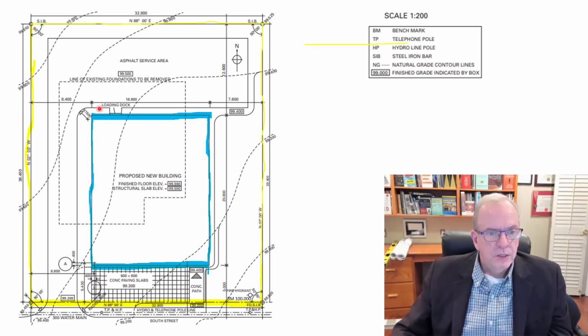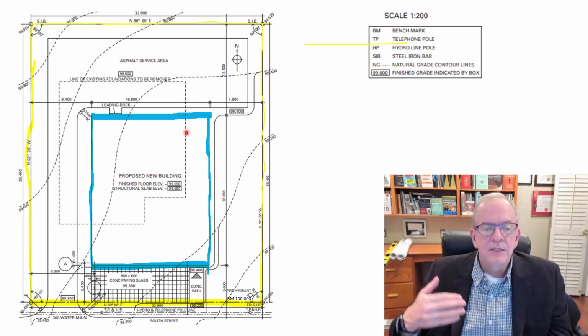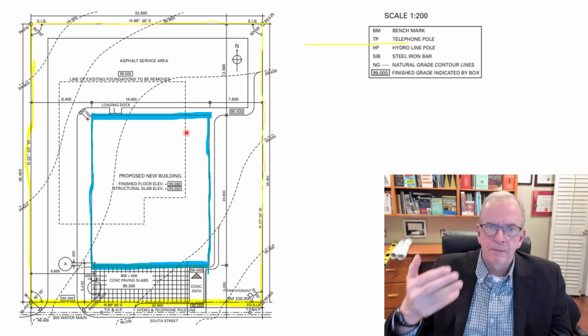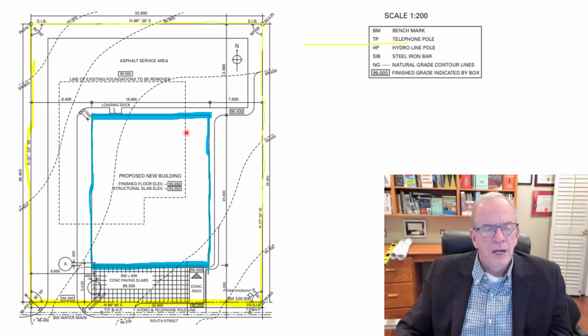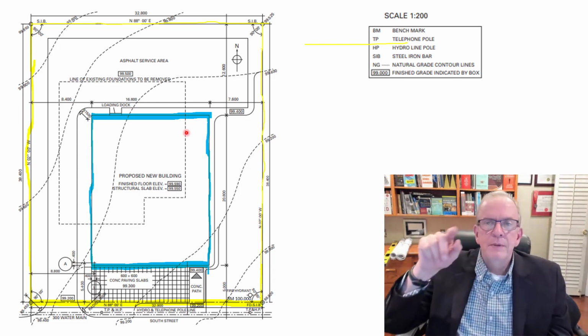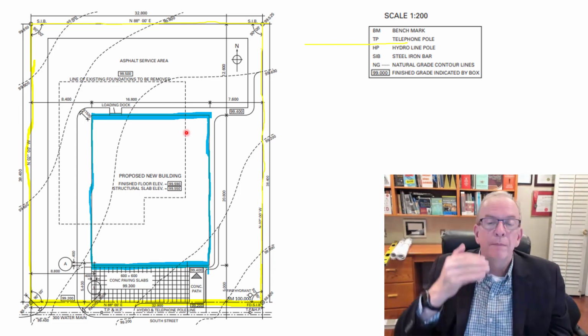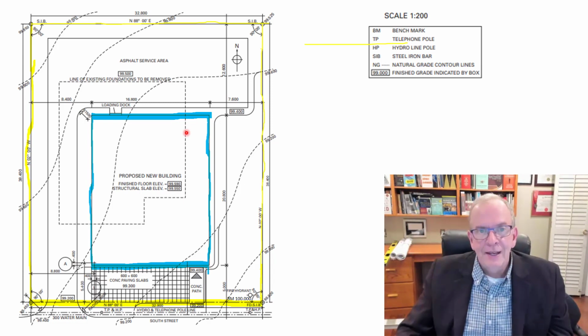All right. So we have that. We're showing that we would remove the existing. These dashed lines mean a lot of things in construction drawings. They can mean hidden lines, and that usually means something that's behind something. We'll get into that more as we go further in the course. It could mean vents for plumbing pipes, which are usually a dashed line. It could be describing something that is an option, that if you want to pay extra for it, you can get it. It could mean that there is something like this that's to be removed.